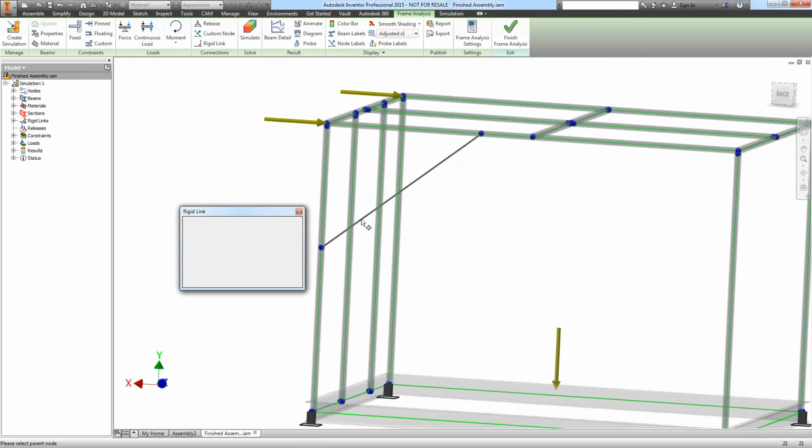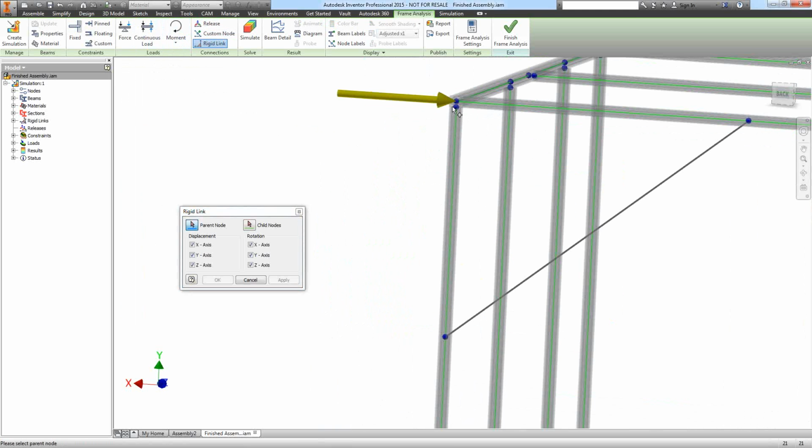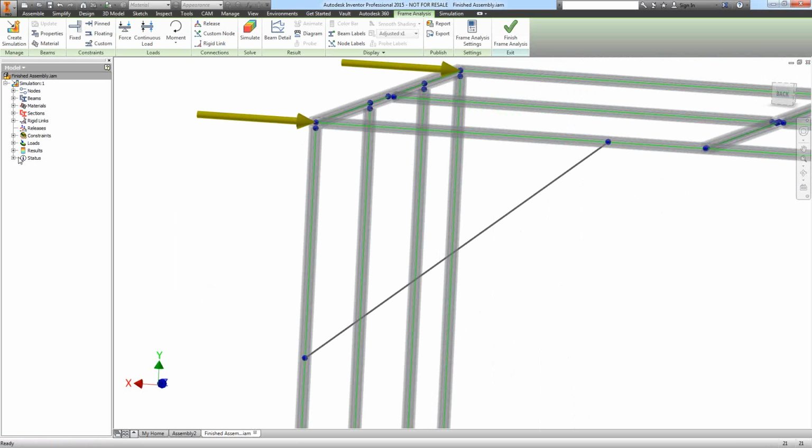Ultimately, I think the reason this didn't necessarily get so well tied up, if it was around this entire corner here, yeah, I think you would try to tie these three together, so you would tie this one to the parent up here and then tie that one to that one. That's how you would do it if it was a gusset, because ultimately you're saying that these nodes aren't allowed to move relative to each other, adding rigidity to the frame.